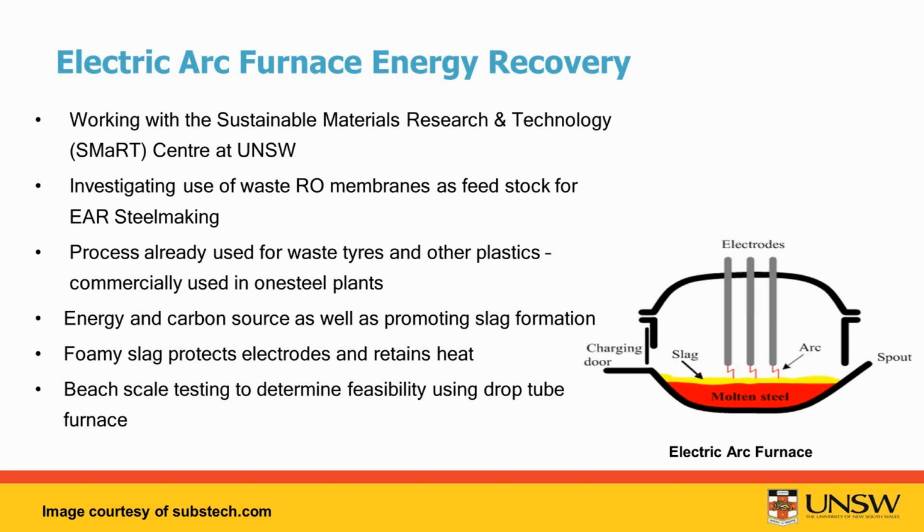And as the steel making process requires a coke as a carbon source, they inject metallurgical coke directly into the molten steel. Now, as one of the many reactions that happen in that molten steel, the carbon reacts with the oxygen in the system to produce carbon monoxide and carbon dioxide. That bubbles up through the molten steel.